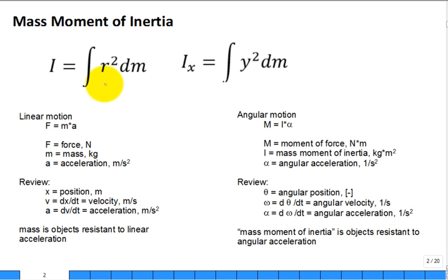So anyway, here are the equations for I. You can have it around a particular axis, or a lot of times it's around a particular point in 2D, and that axis is coming out of the paper. All right? So maybe you write it like that. Here, what do they have? R, the distance from that point, where the axis is perpendicular to the paper.